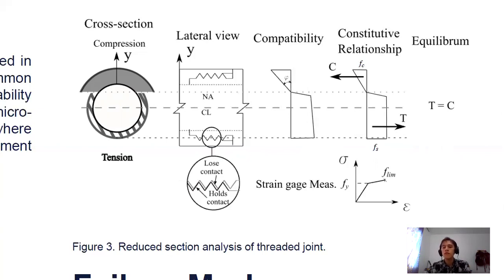So in this methodology, we can find out what the bending capacity or moment capacity corresponds to each failure mode. If we set up this tensile stress here as the rupture stress or as the jump out stress, we can solve what the compressive stress must be to accomplish equilibrium, that is, the tensile stress resultant equals the compressive stress resultant.